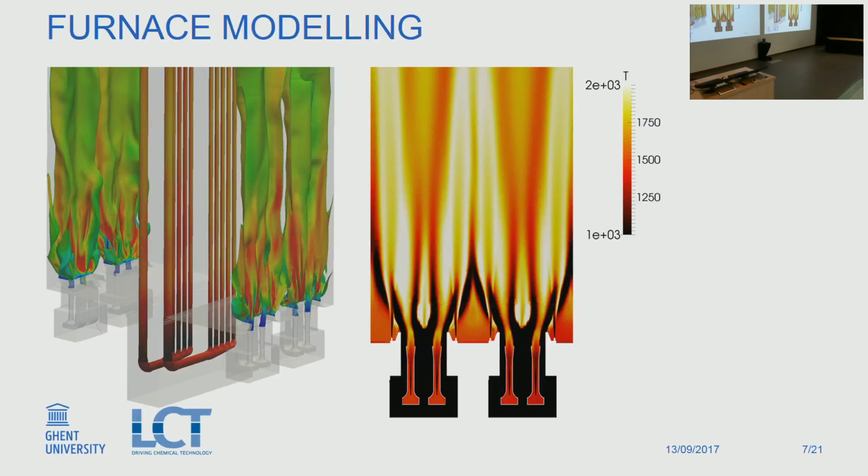So this is part of these are the complex burners, and what comes out is the flames, and that's an isosurface of CO concentration colored by, in this case, velocity, I think. So this is a way to visualize the flame structures in the furnace, and you can see that they're nicely close to the wall. It's what you want, because if you have flames impacting your reactors directly, then temperatures would be too high and you would actually melt the reactors that are inside.